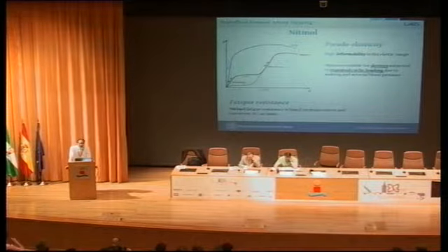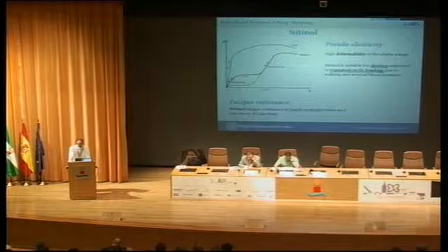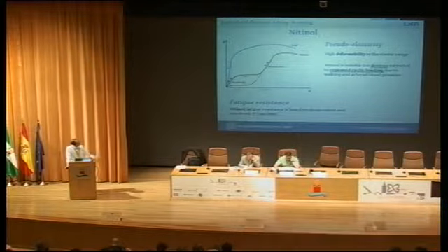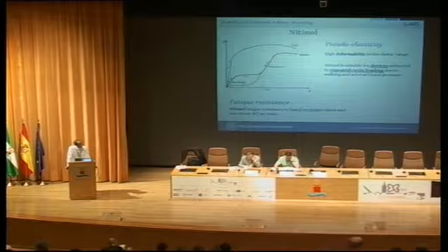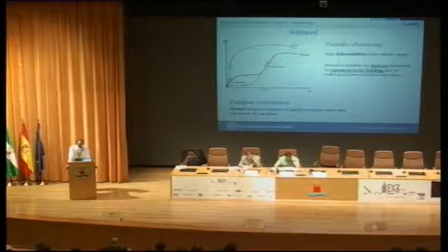The material used for the stenting of superficial femoral artery is nitinol, a shape memory alloy, which is able to have high deformability in the elastic range, and this material is suitable for devices where we have repeated cycling loading due, for example, to the walking and the arterial blood pressure. But in this particular district, the most important one is the walking, more than the arterial blood pressure. If we want to evaluate the long-term behavior of the device, we have to think about the fatigue resistance.